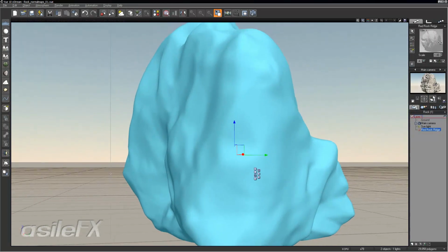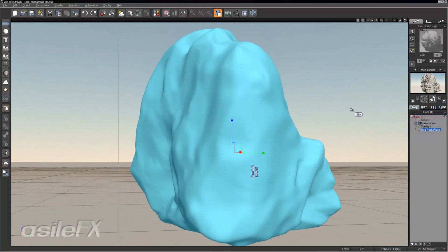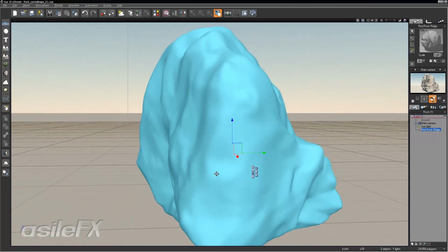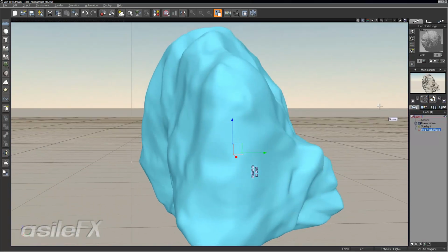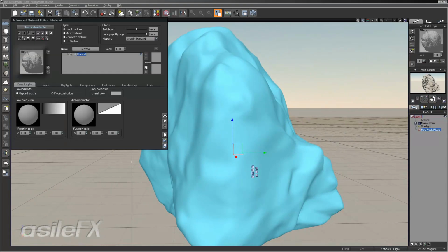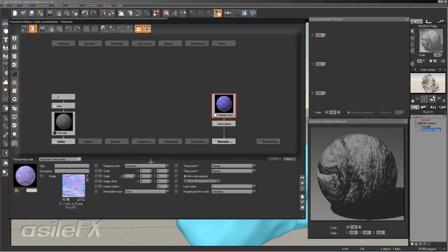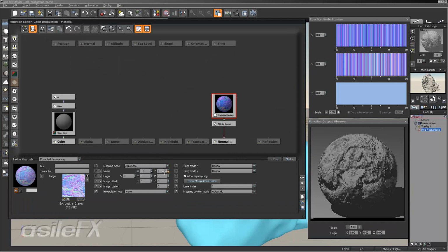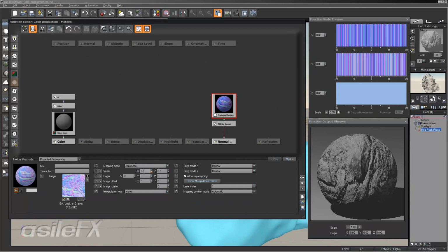I'm going to go ahead and just rotate the camera a little bit and take a look at this from a different view. Now I found that you can get away pretty easily with a texture map that's 64 pixels by 64 pixels, and then just kind of repeat it. So set up a seamless texture normal. And we can just reduce the X and Y to 0.5.